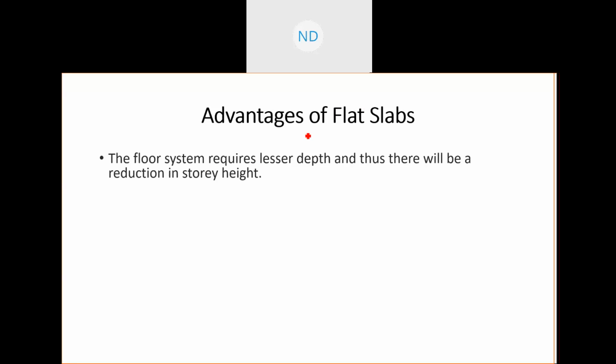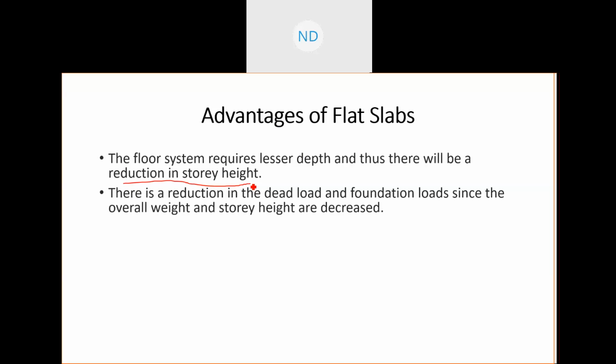I mentioned this. When we use flat slab, we are reducing the story height by removing the beams. Next, there is a reduction in the dead load and foundation loads, since the overall weight and the story height are decreased.